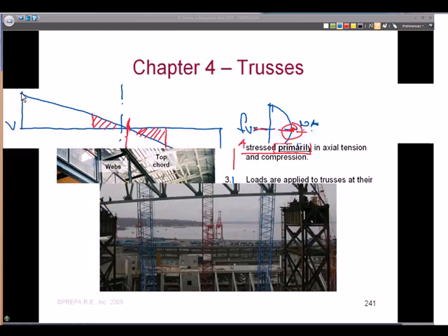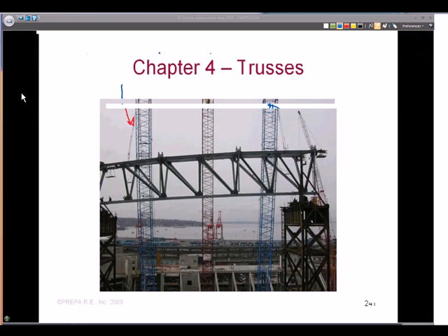When you start to get into larger members, such as some of these stadiums or longer span trusses with heavy members, these members have a self-weight to them as well that has to span in between here. And in these bigger trusses, we better not overlook the self-weight of the top and bottom chords that act as beams between these members.